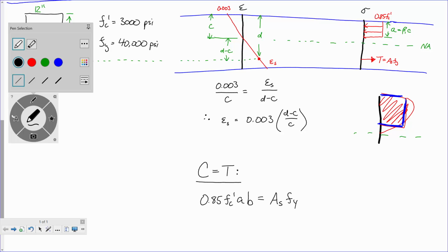That make sense? Now, we know that f'c for this beam is 3,000 psi. We know the beam is 12 inches wide, and we know the area of steel. Well, let me ask this. Let's talk about the area of steel. What do we have in this beam? 3 number 9. So, first page, we have our ASTM standard reinforcing bars. We are dealing with number 9 bars. So what's the area of a number 9? 1 square inch. Remember that? Number 9s always made my life easier when making problems because number 9s were 1 square inch. So 3 number 9s are 3 square inches.